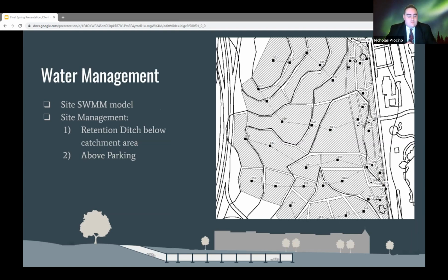For water management, we use stormwater management modeling, or SWMM, and green infrastructure flexible modeling, or GIFMod, to analyze our water management. SWMM was used to look at runoff across the entire site to prevent flooding of the roads. Across the bottom of the slide, you can see a section of our site from North Capitol Street to Harewood along the second path shown in the SWMM model to the right.